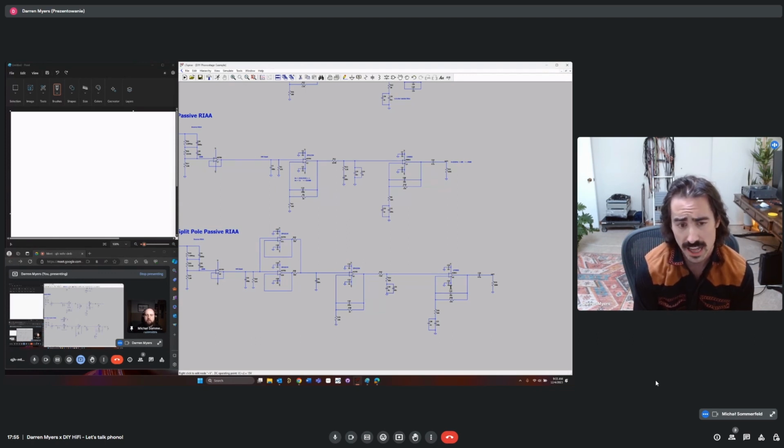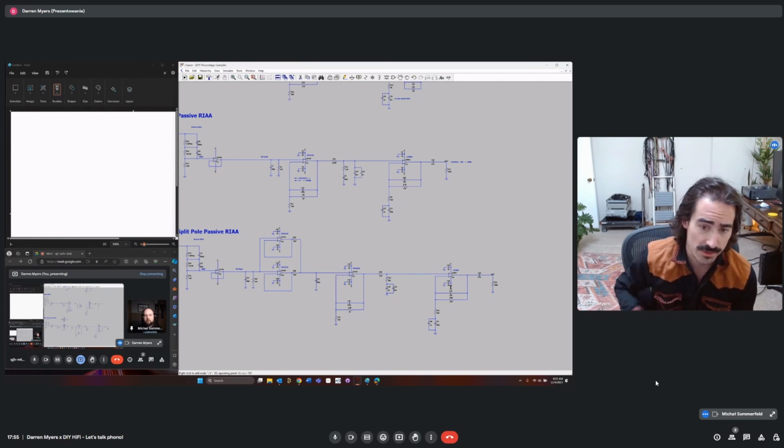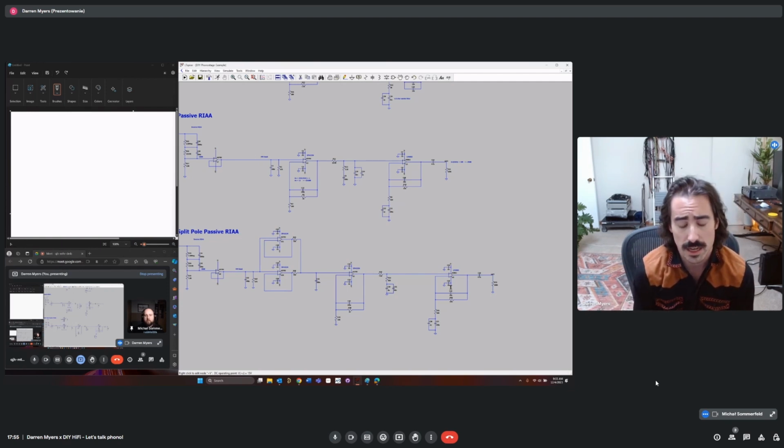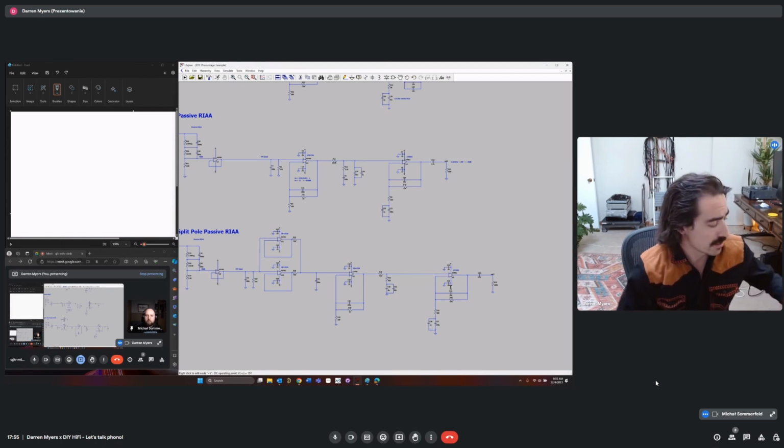An LM317 really doesn't have much bandwidth at all, 100 kilohertz maybe. But there are more advanced, higher performance regulators on the market that can run a megahertz plus of decent rejection. I'm not talking about a 3 dB bandwidth spec, but just having decent rejection up to a megahertz. You can find those.